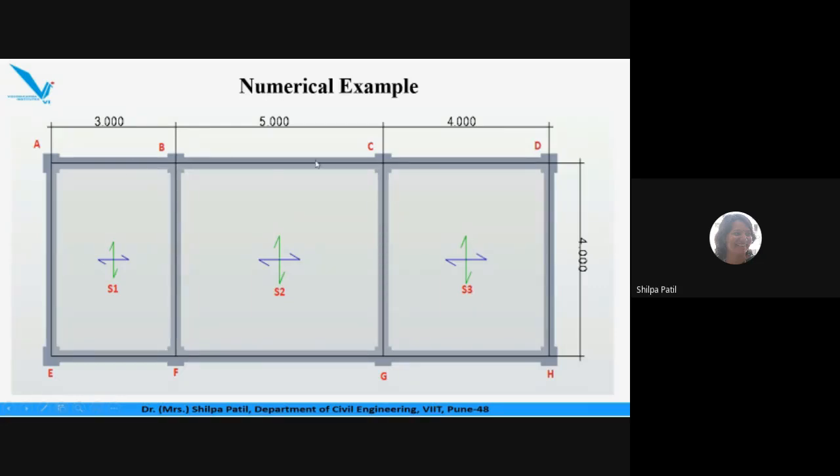and this beam behaves like a flange beam again. But now here in this case it is an L beam, because there is nothing on the other side of this beam ABCD. This is a plan. So there is nothing on the other side of the plan of the beam ABCD. So this beam will not behave like a T beam. Okay, it will behave like an L beam.